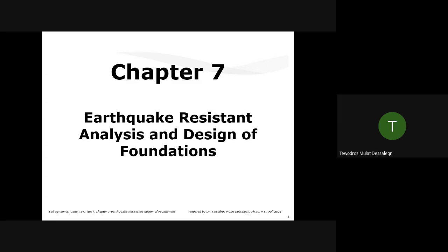Similar to the static analysis and design, during seismic loads you'll have some additional load because of inertial and kinematic activities. There are mainly two ways: a pseudo-static approach, and a fully software analysis or equivalent linear analysis using Plaxis or FLAC or other geotechnical software to get additional earthquake and seismic loads.